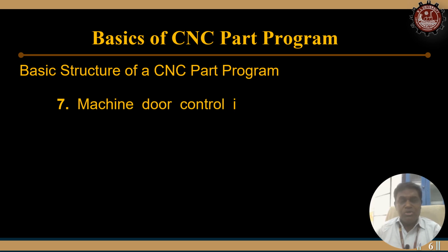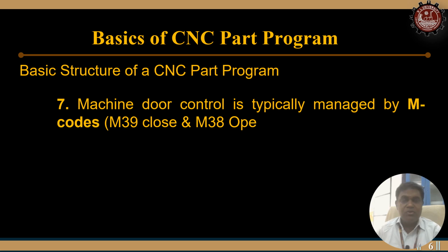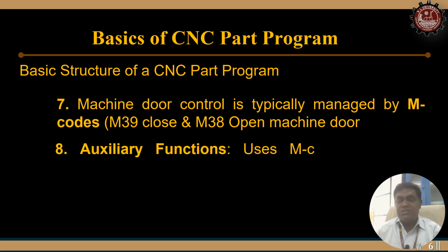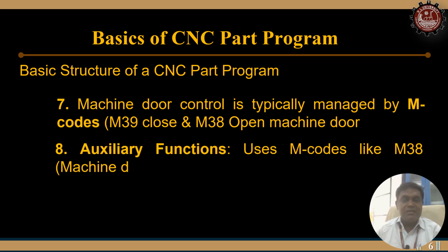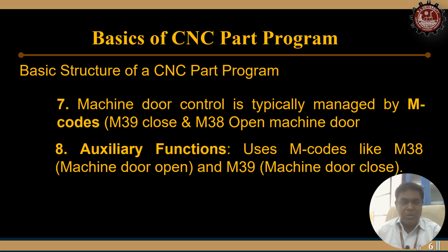The machine door open or close can also be mentioned using M codes. M39 is close and M38 is open the machine door. And auxiliary functions use M codes like M38 machine door open and M39 machine door close.